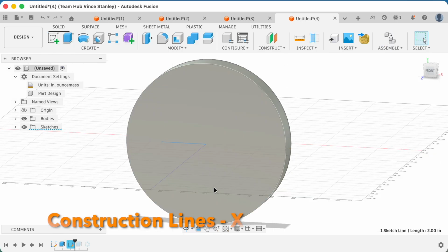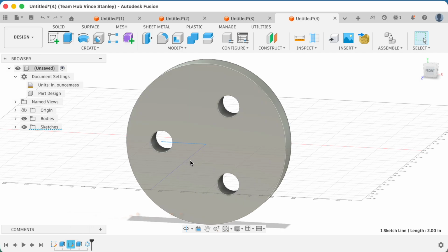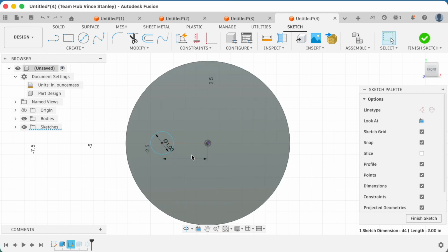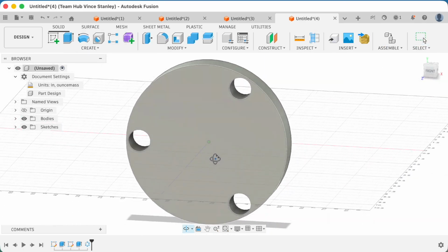So when we finish sketch here, I can extrude it like here, and I did a pattern. But if we don't happen to like this pattern, this allows me to back up and change this to a different number here. And then all the later steps will populate.